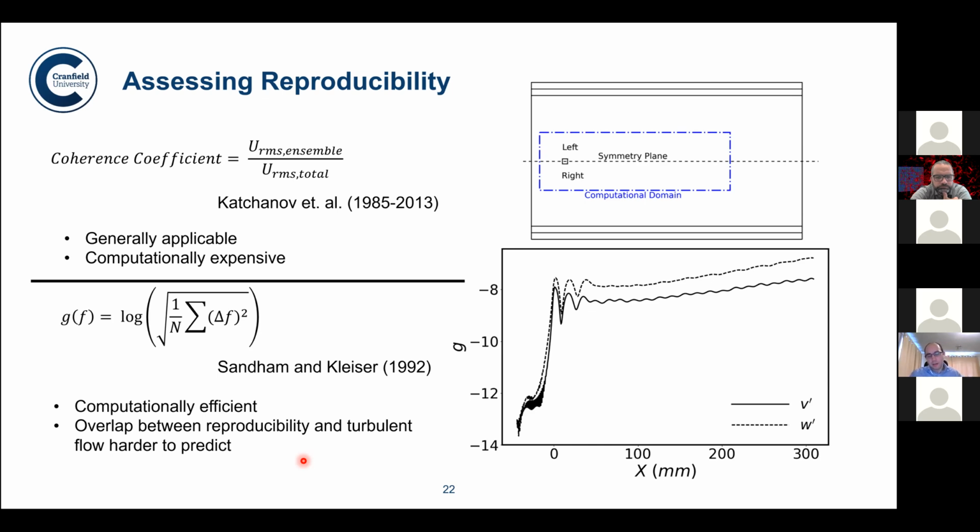So, doing an experiment with measurements until we reach statistical convergence for the RMS values, and then repeating that experiment between 30 and 50 times, and basically comparing the different repetitions with different noise profiles and assessing whether the statistics done on that collective record as a single long experiment is the same as the one which is ensemble averaged of the separate experiments.